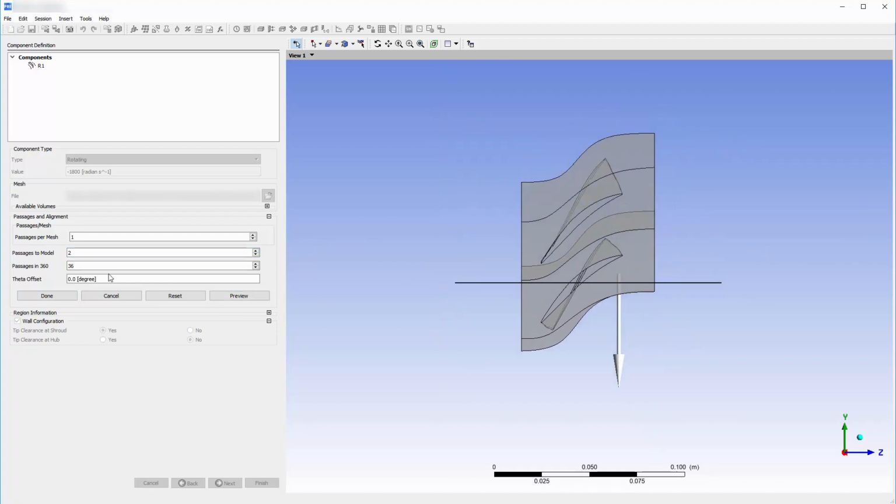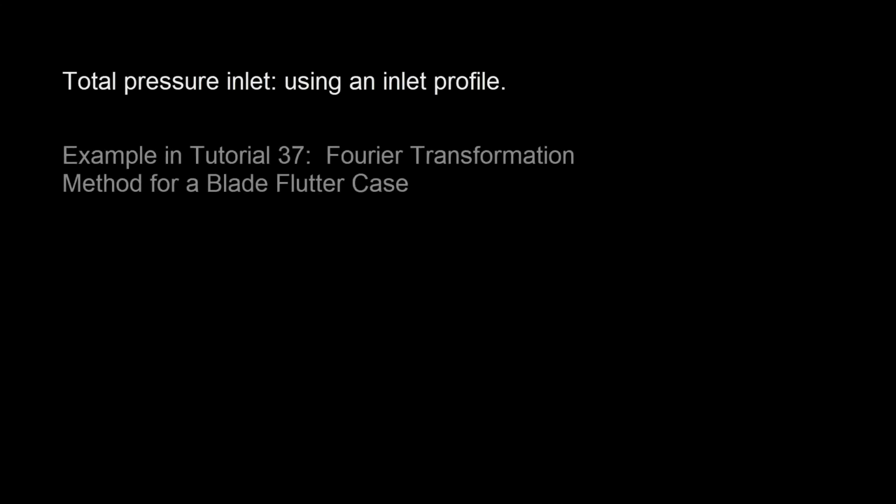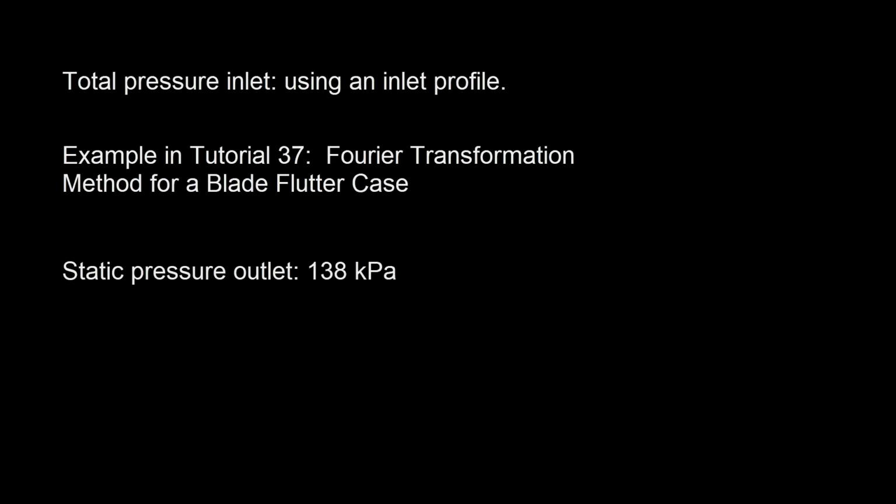It looks good, so I'll click Done. I've applied a total pressure profile at the inlet. More detail on how to apply a profile boundary condition is shown in tutorial 37 of the CFX documentation. I'm also using a static pressure outlet of 138 kPa utilizing radial equilibrium pressure averaging.